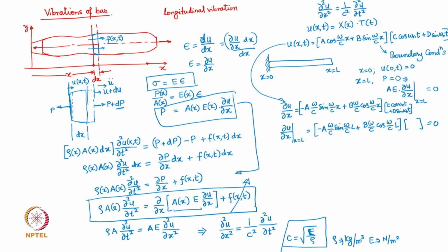Now, what is the substitution of the first boundary condition? We know that u at x equal to 0 is going to be 0, which gives A plus b is 0. So A into the harmonic time function, C cos(omega_n t) plus D sin(omega_n t), is equal to 0, which means that at all times A has to be 0. That is quite similar to our stretched string case.